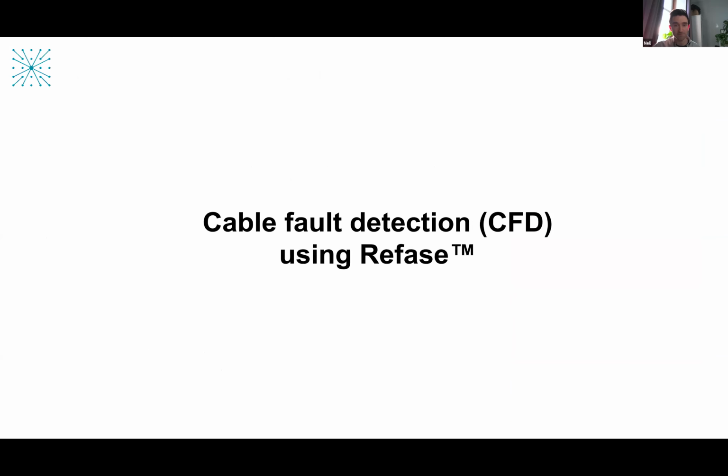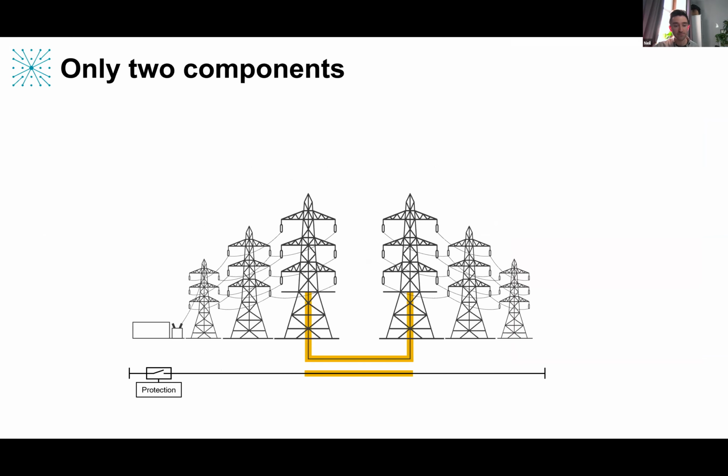Yep, thanks, Campbell. So I'm just going to talk about what Synaptec's approach is to solving some of these problems. So this will be using our rephase system to do cable fault detection and enable auto reclose at a distance and enable differential protection at a distance, as Philip says. So our approach to this is relatively simple, we think, requiring only 2 hardware components to be installed.